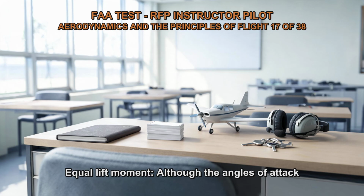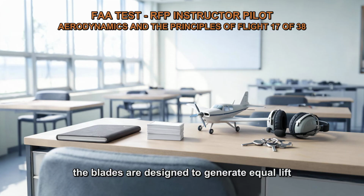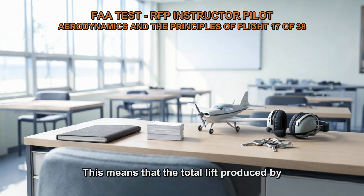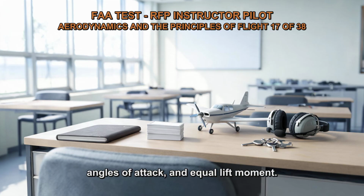Equal lift moment: although the angles of attack and airspeeds are different for each rotor blade, the blades are designed to generate equal lift moments. This means that the total lift produced by the rotor system is balanced, resulting in a stable and level flight. Therefore, the correct answer is unequal airspeed, unequal angles of attack, and equal lift moment.